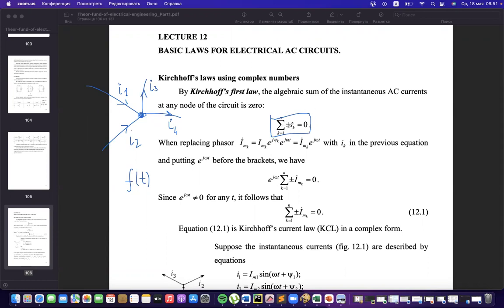For instantaneous values and functions, we use small letters. Or you could use vectors in complex form. A vector is a constant value, and that is why we denote it with a capital letter. It will also be true in any form that you want, either as a time function at some point of time, or as a vector, as the root mean square value, the effective value of this sinusoidal function.